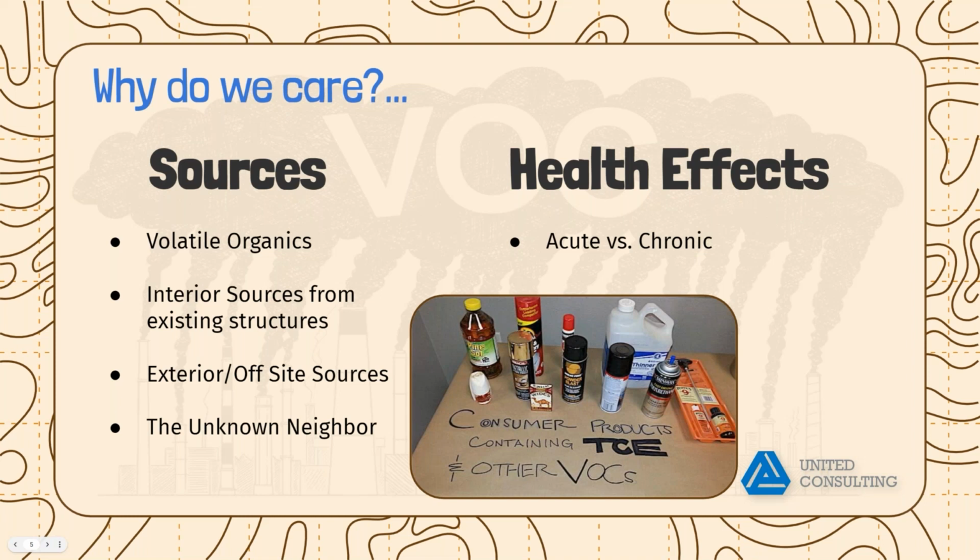Thus, investigations of the vapor intrusion pathway and risk assessments are needed to develop a conceptual model and evaluate that risk into the future. In some situations, this can be complicated by the presence of some of the same chemicals in household or business products, such as solvents, paints, gasoline, dry cleaning clothing, and cleaning agents. These products may pose, separately or combined with vapor intrusion, a human health risk. When evaluating the potential for VI or an active VI situation, we immediately look to a checklist of potentials to rule out. In some cases, the risk can be literally right under your nose.